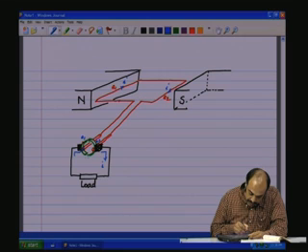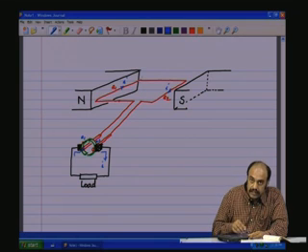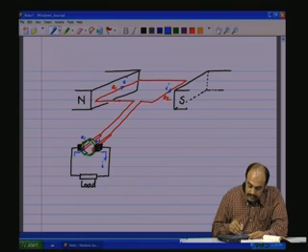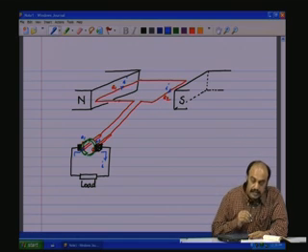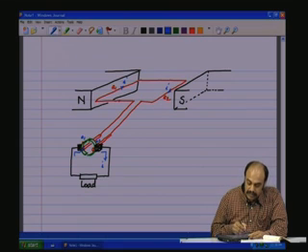So the A2 portion of the ring is going to be in contact with this left brush, and the A1 portion is going to be in contact with this. But when it has crossed over the orthogonal plane, there is a reversal in the current for A2 and A1, and therefore A2 becomes positive and A1 becomes negative.